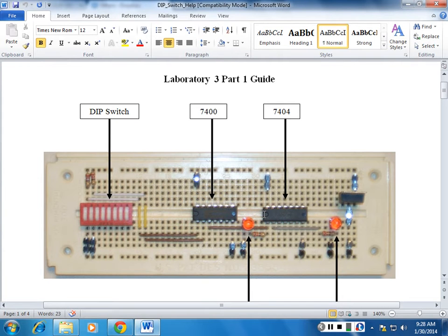The reason we placed it in the middle is because there is another strip here. There's a blank spot here. Do you see the blank bar here? No, with no holes. We place the ICs here because we want to make sure that one side of the pins are not connected to the other side of the pins, because we know that everything here is shorted along the column, right? But these columns are not shorted with these columns. So we place the ICs along this strip, okay?